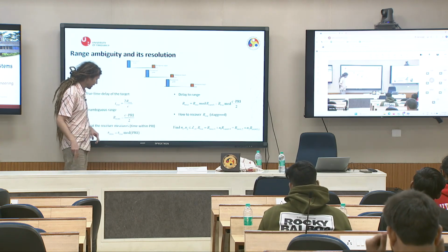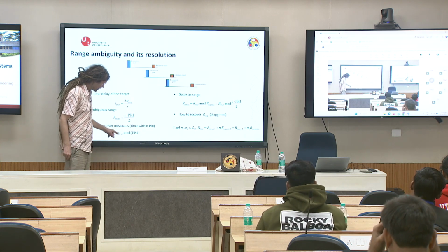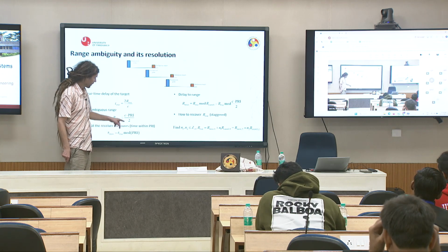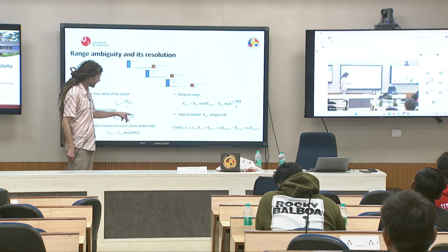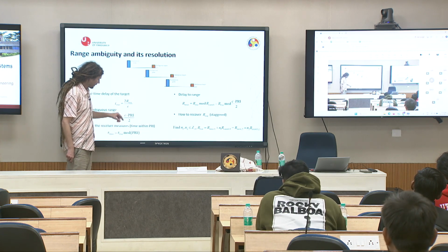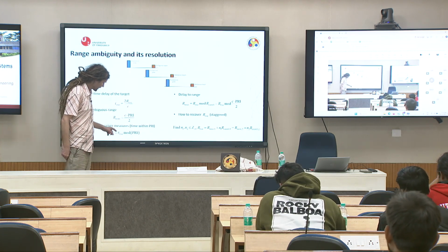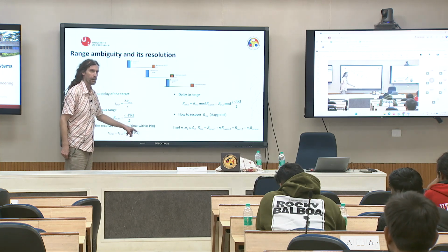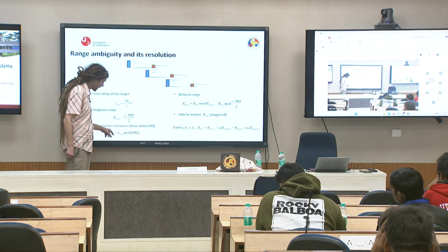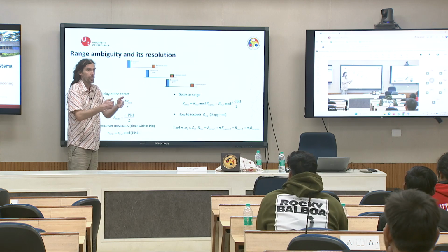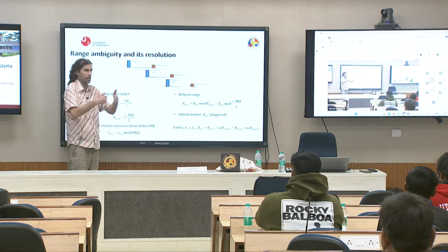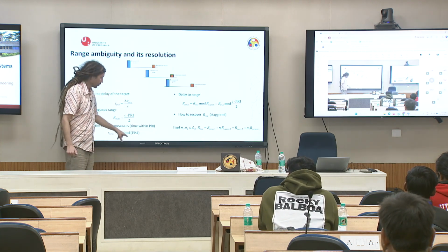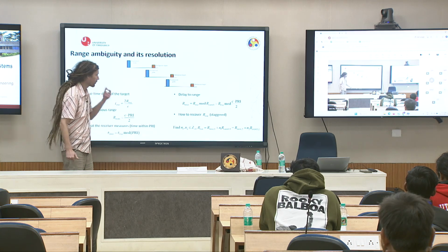So imagine this corresponds to a true time delay of a target 200 kilometers away, but my unambiguous range is defined by PRI and is shorter than this time delay, so my radar sees the true delay modulo PRI by some value. As a result, the measured time delay will be much lower. And what does that mean? I will see a target at a slant range closer to me, but it is not true. It is always just modulo PRI.